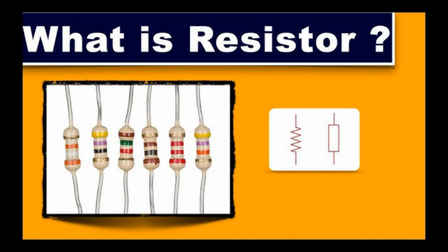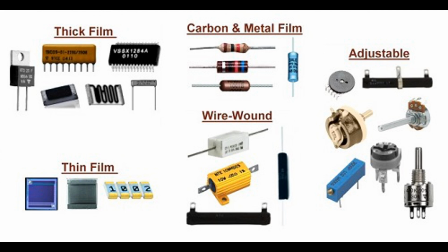Preventing signal distortion. Purpose: impedance mismatches can cause signal distortion, especially in high-frequency circuits. Matching impedance helps maintain the integrity of the signal. Example: in digital circuits, impedance matching on high-speed data lines ensures that signals are transmitted without distortion, preserving the integrity of the data. Techniques for impedance matching.